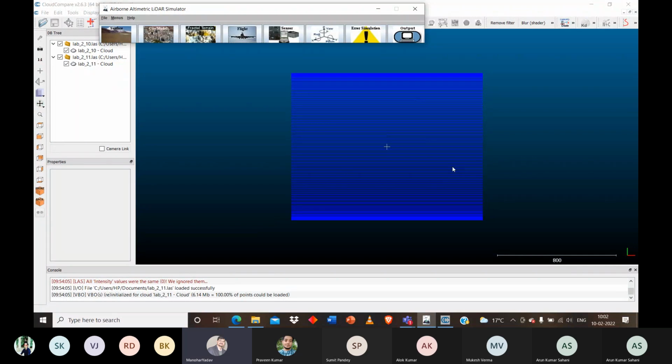We have been discussing airborne LiDAR. If you see the LiDAR system, when it operates, we perform this laser scanning through a mobile platform. In that case, the LiDAR system comprises a laser scanner, that is a 2D scanner, as well as a positioning and orientation system. We'll learn later on how the data collected by individual sensors are combined together.